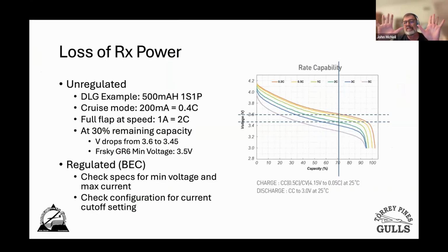So all those fire things are, you break a wire, you short a wire, you crash. They're real concerns. You need to think about them before you get too crazy optimizing your wire size and everything. Okay, this is that same battery capacity curve.